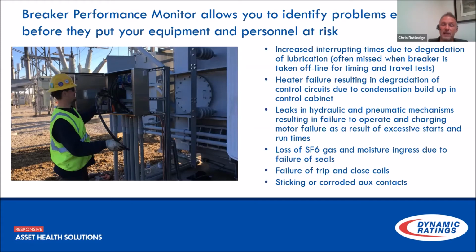Loss of SF6 gas and moisture ingress due to failure of seals, failure of trip and close coils, and sticking or corroded aux contacts. These sticking contacts will result in a lot of coils being burned up, as that is what energizes and de-energizes that trip coil during that event.